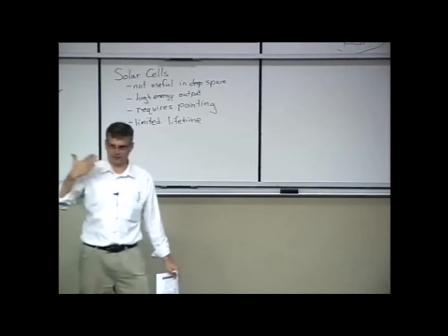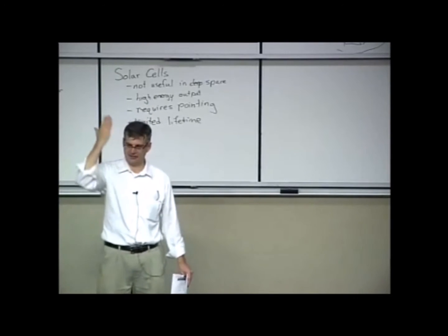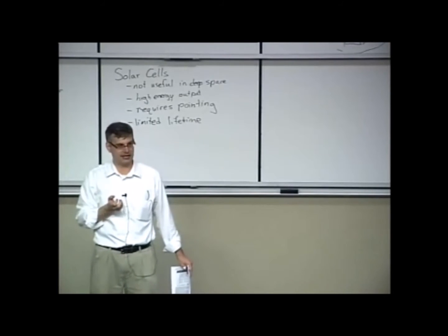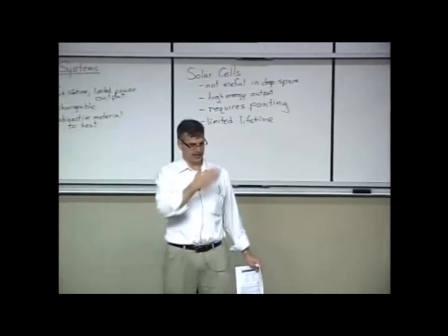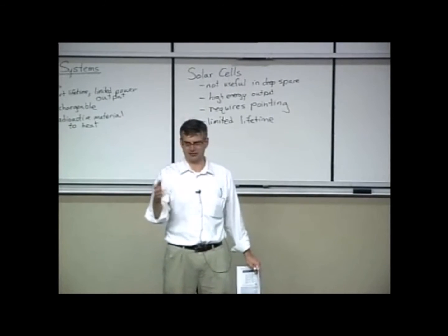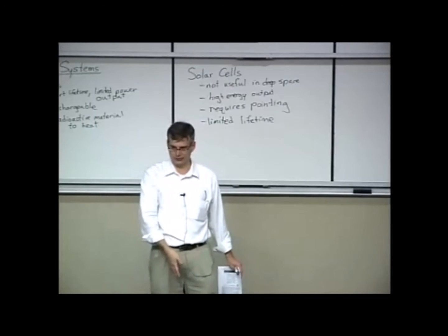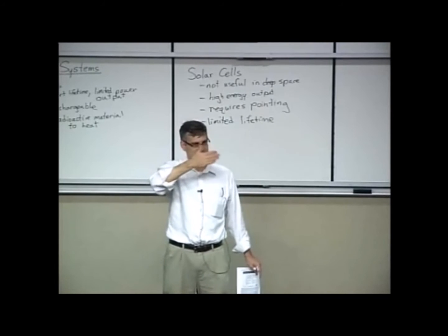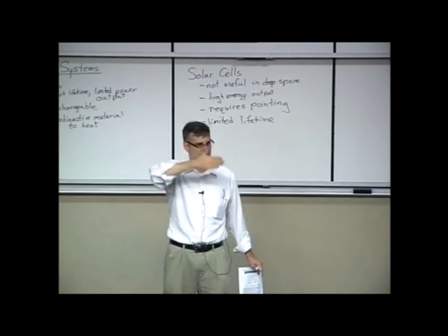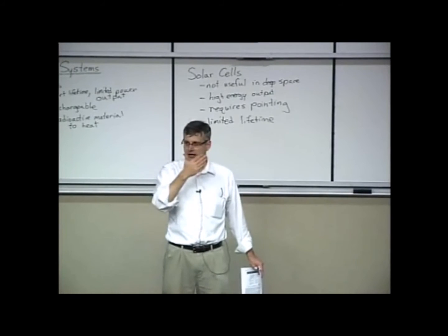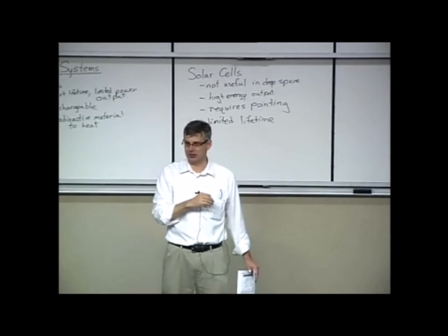And if you're familiar with constructing a solar cell, you've got to have sort of an encapsulant that's transparent, that allows light to come in and strike the PN junction, and then another encapsulant layer that completes the circuit but is optically transparent, something like indium tin oxide that you can put on the surface of that, and then the encapsulant. So you have to have these nice transparent substrates that go on top of where the PN junction actually does most of its work.